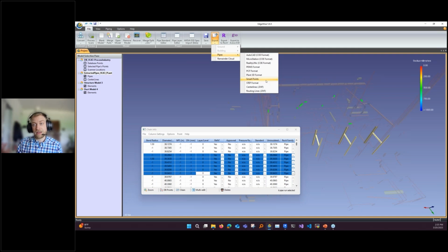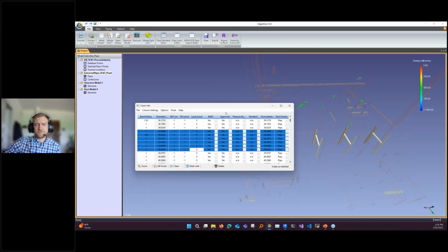So if adding valves and flanges is something you would rather do inside of Revit, instead of bringing your entire point cloud in, you can export just points near your pipe models for the systems you want to work in, and only view that point cloud data inside of Revit, which could be maybe a gig for a big job if you've got lots of pipes, instead of hundreds of gigs potentially for a really big point cloud. So that one's a great one.